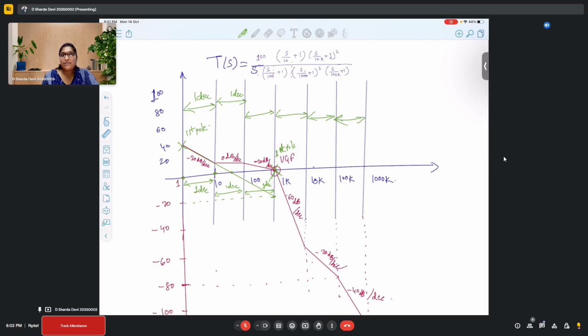And alternatively, if a Bode plot is given and you have to find the transfer function, you will find the transfer function based on the poles and zeros. And from there, if it is not in the starting place, between zero frequency and your first pole or zero, until then it is fine, right? There is no issue.